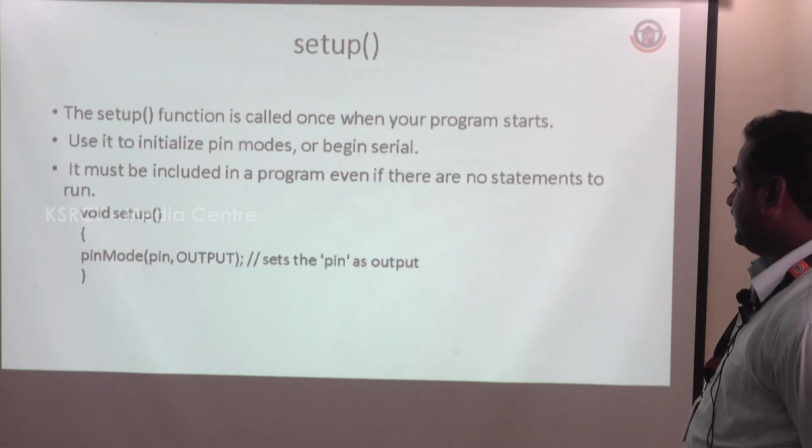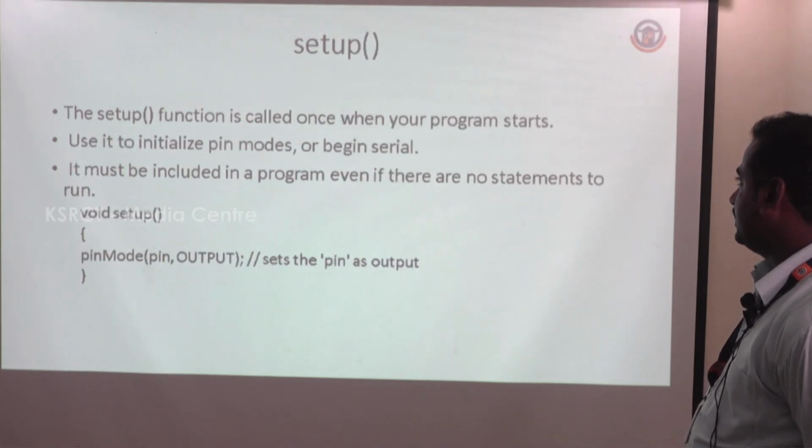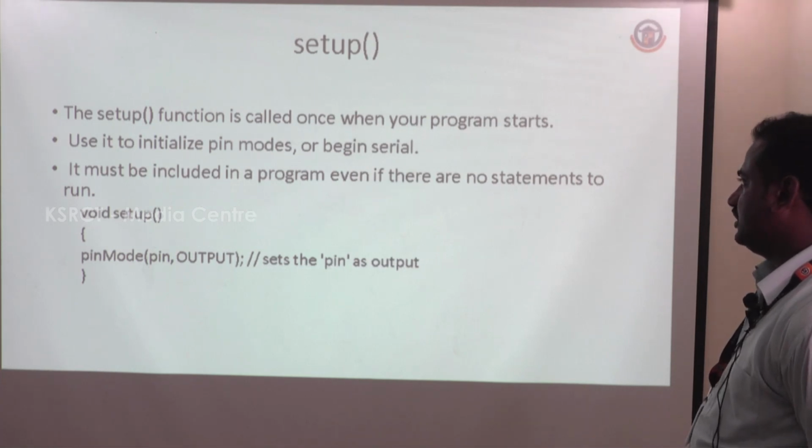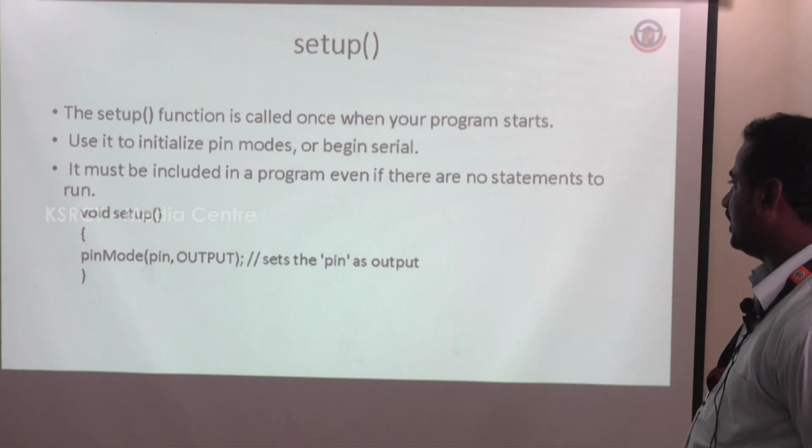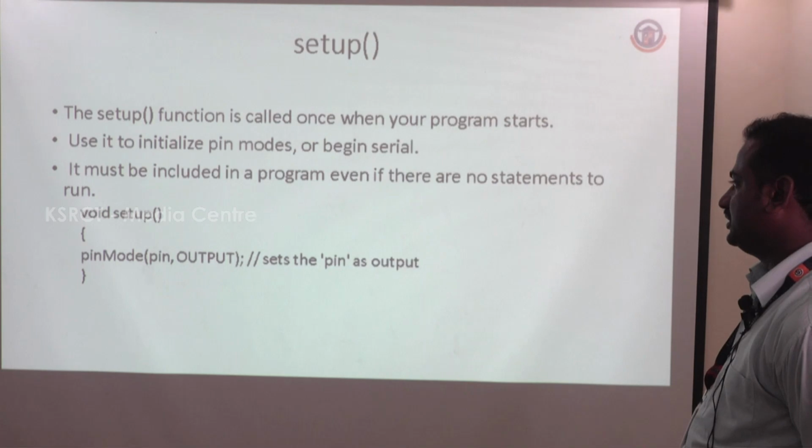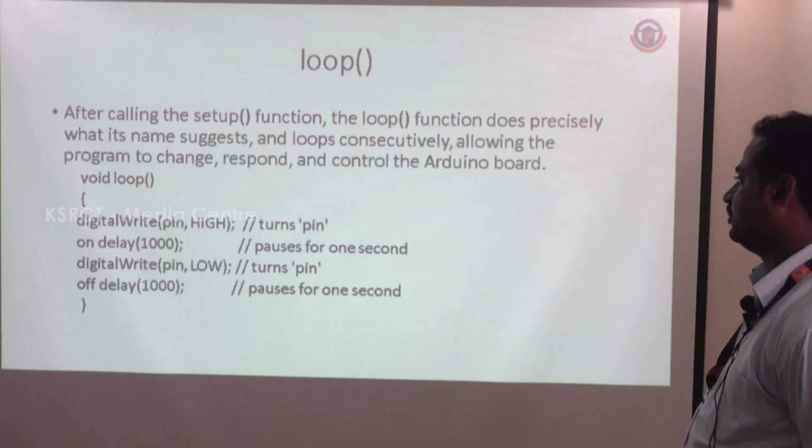Next, the setup. The setup function is called once when the program starts. Usually it initializes the pin modes or begins serial communication. It must be included in a program even if there are no statements to run. Void setup, and open the curly braces, so that is a pin mode.